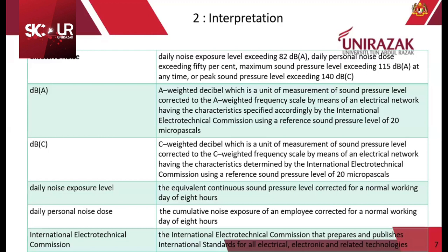And then kita juga ada dalam yang baru, kita ada daily noise exposure, the equivalent continuous sound exposure level corrected for the normal working day of 8 hours. Daily personal noise dose, the cumulative noise exposure of the employee corrected for the normal working day of 8 hours. So mostly kita akan ambil dalam 8 jam lah.